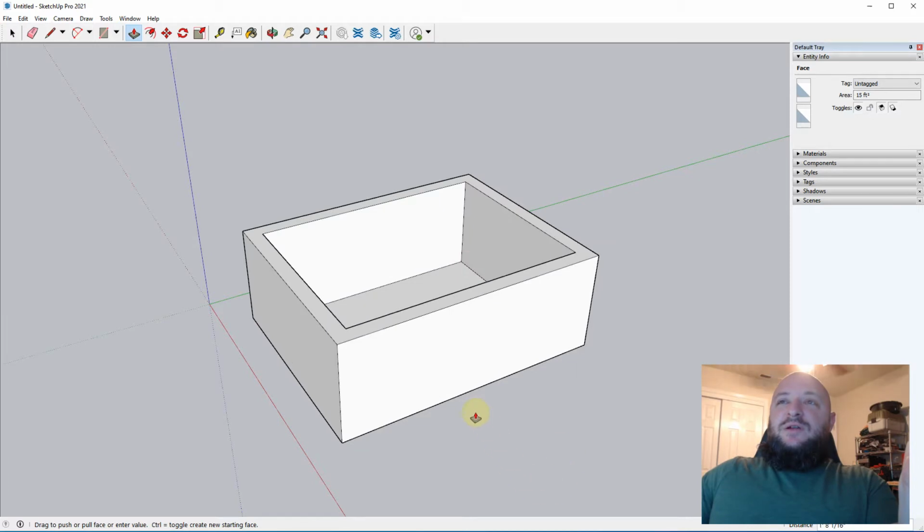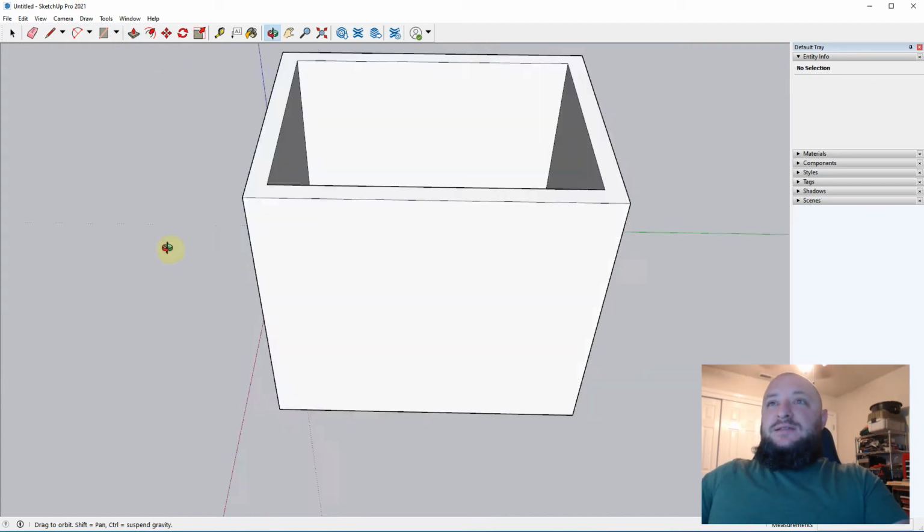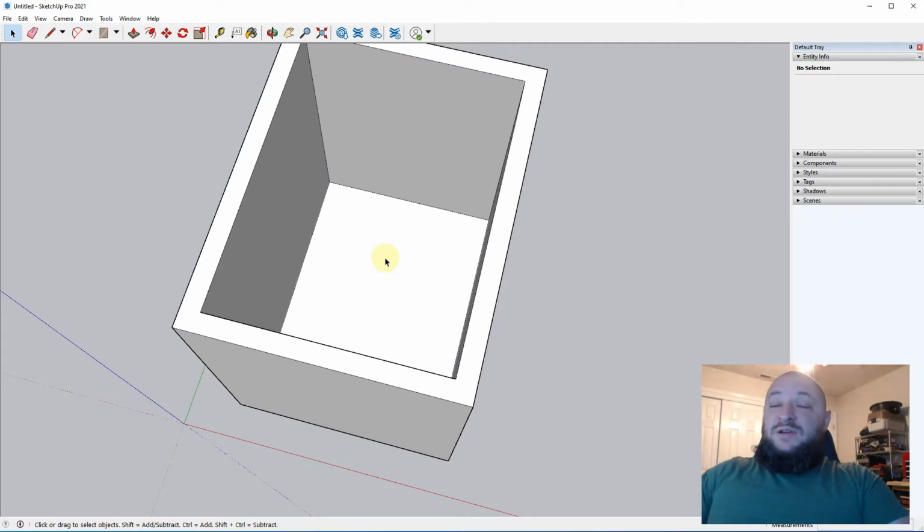And this can refer to other points too, so watch out where you actually use it. And in this case, I'm going to do 8 foot, enter. And so that's going to set this wall up at 8 foot tall, okay? So, very simple, a couple of lines, and we already have an established space.